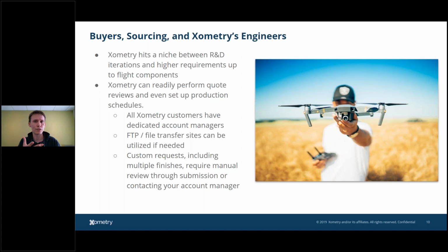the specs grow. So at first it may be a part that ultimately could be a titanium milled part with different finishes to it, but it may originally be milled out of 6061 or something for some component testing and something that brings you up to kind of a lower mid fidelity model, before we move to the much higher priced exotic materials and specifications behind it. So we often see that kind of pragmatic approach of prototype to production, but again with added specs in between here.